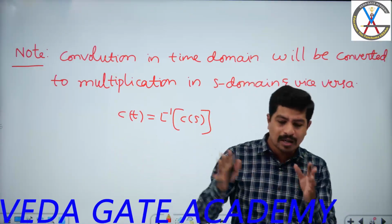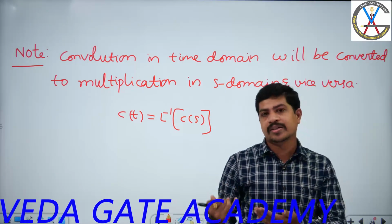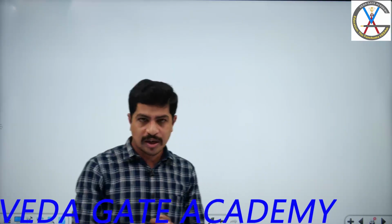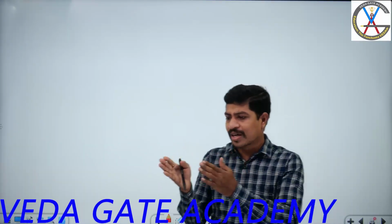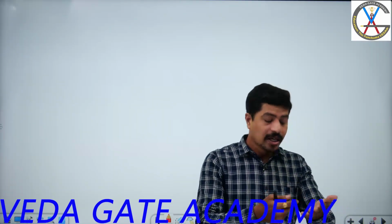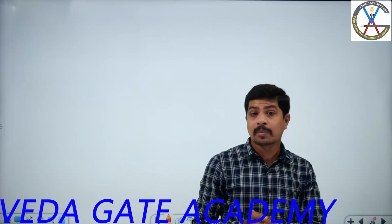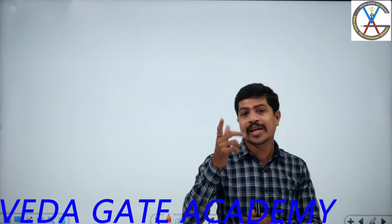So with this, we are done with the representation of RLC without initial conditions. With initial conditions, we have to see. There are some problems where initial conditions will be given. In transient analysis, if a transient question looks very difficult in time domain approach, where you write I of t as some equation in terms of t, that may become difficult. At that point, S domain analysis is going to give the answer very easily.